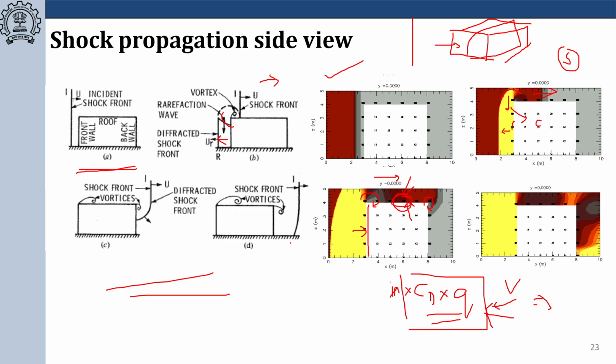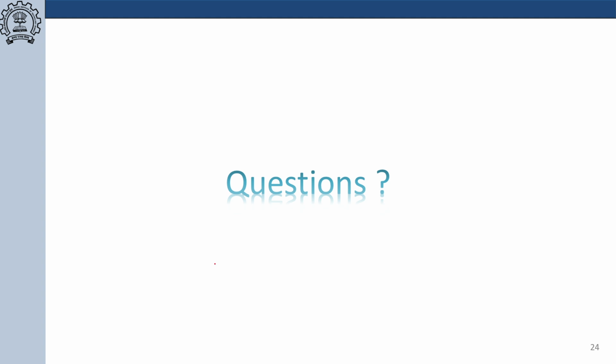And as you can see, the shock wave moves forward and the pressure decreases. Again the vortex region is formed here. So this is how you simulate your cases, your shock propagation. You should be careful while simulating the data. This software is capable of generating the typical shock scenarios and explosive scenarios, with the limitation of a complex structure. You cannot simulate a complex shape of the structure or of the charge. For simple shapes of structures and charges, you can simulate the explosions.